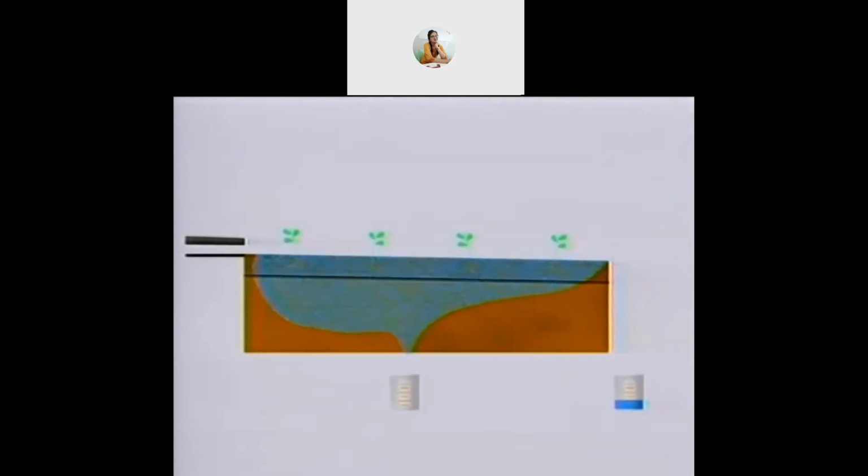What are the disadvantages? First, initial cost is more and is increased further if tiles or pipes are laid. Second, there is a loss of cultivable land occupied by trenches. Third, in this method, it is not possible to add manures and fertilizers. D. The perforated pipes may get choked. E. Waterlogging can occur. And F. Water with high salt content can't be used.